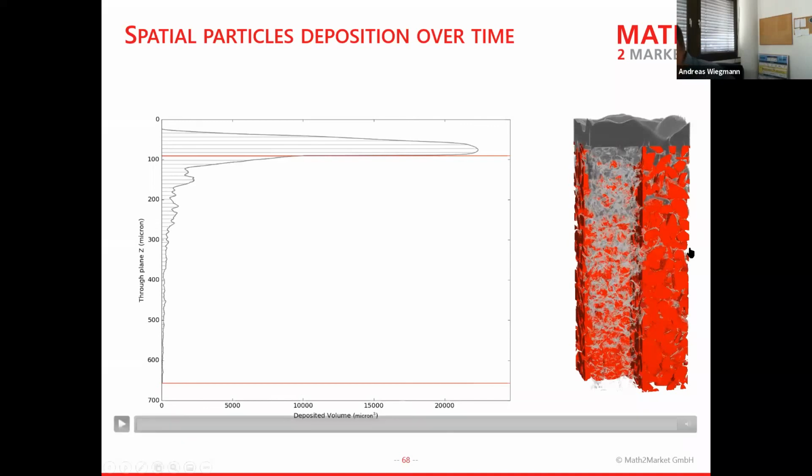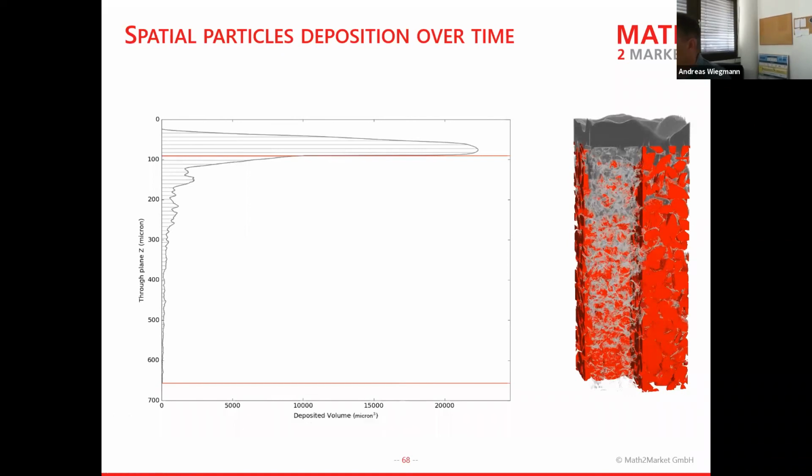So how would the design work? Well, you see how this works, and then you're changing, say, the grain size, or you're creating a gradient in here, or usually there's a wash coat on top, so you change the top layer here, and you see in the computer how much soot gets trapped on the bottom, what's the flow resistivity, etc., during the simulation. Good question. You gave me a chance for a long answer.